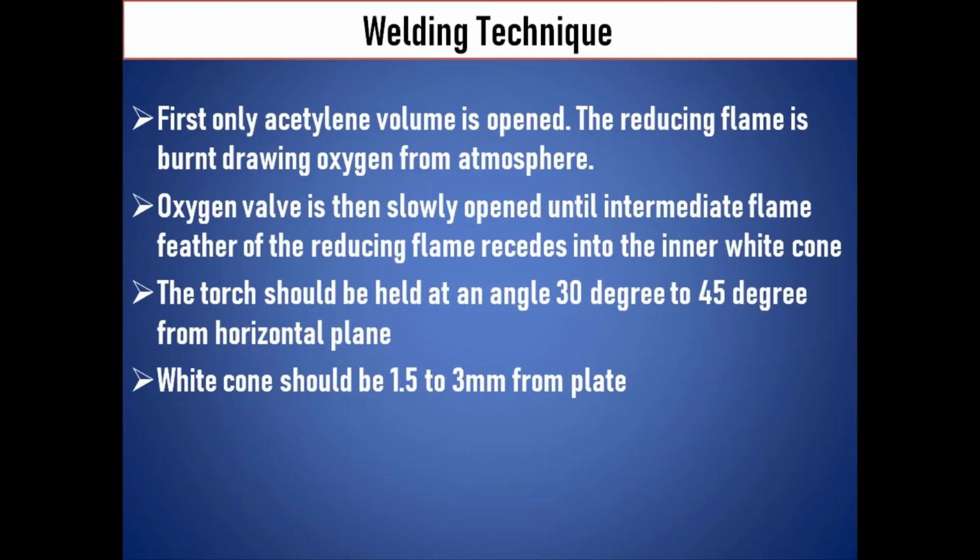Now, as I told you in one of the previous slides, while doing the welding process, first the acetylene pipe is opened. Then the acetylene will burn with the help of oxygen from the atmosphere, and obviously in that case oxygen will be less, so the flame will be a reducing or carburizing flame.